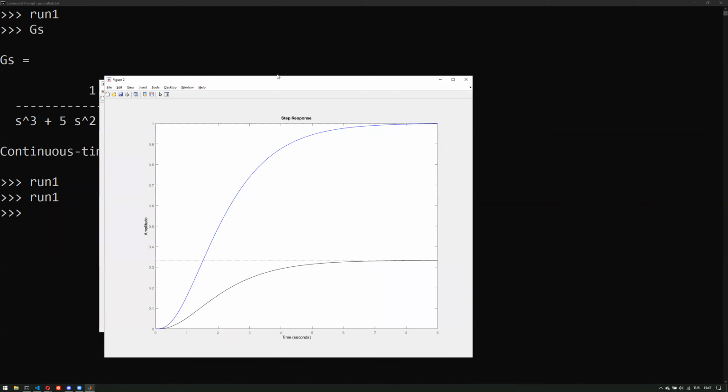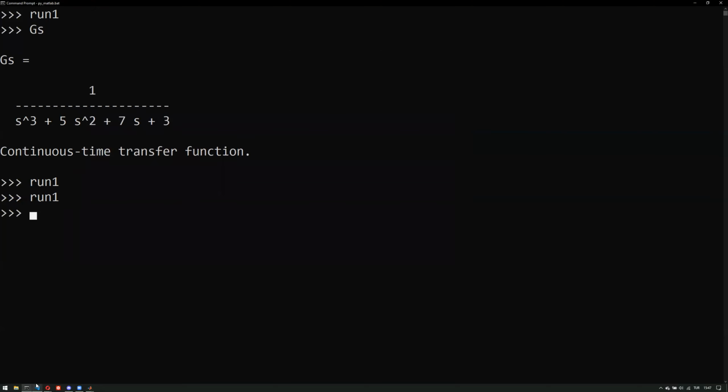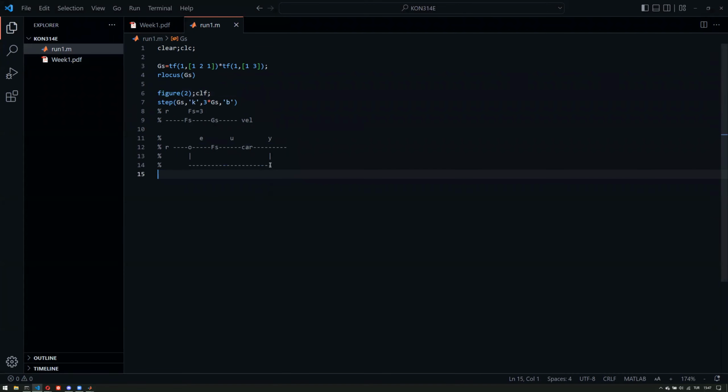But if there's, for example, wind, if there are model errors, or certain other things that are not really taken into account at this point, then your open loop control strategy, since it doesn't measure the output, will not be able to compensate, because it doesn't know that it should compensate, first of all. So you need measurement in order to detect these types of changes in output or modeling errors. So therefore, we need to measure the output and take it into consideration, and it is all possible with this basic structure here. This is exactly that.